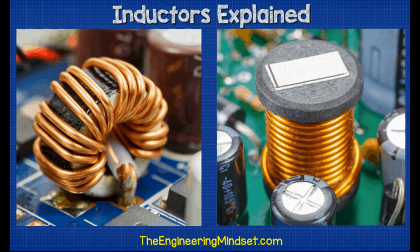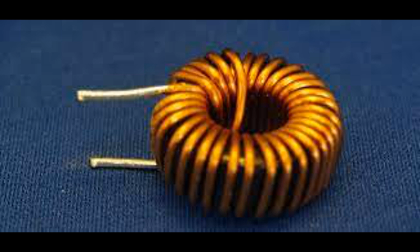Induction heating. Application. Transformers are used in induction heating systems to transfer energy to a workpiece by inducing eddy currents, which generate heat. The transformer steps up the current to high levels, enabling efficient heating of metals for industrial processes. Example: in metal processing, transformers and induction heaters are used to efficiently heat metal parts for forging, welding, or annealing.